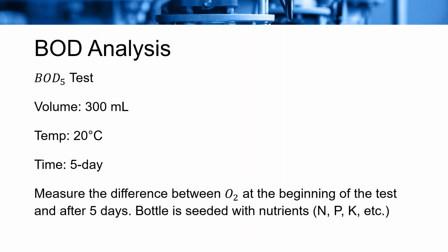So typically how we test for BOD is we perform a BOD5 test. And this is becoming kind of archaic, and chemical oxygen demand is used more frequently. And the industry is always looking for something faster because 5 days is hard to respond to your wastewater.